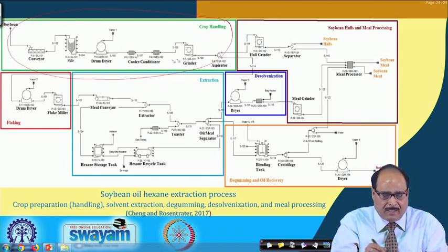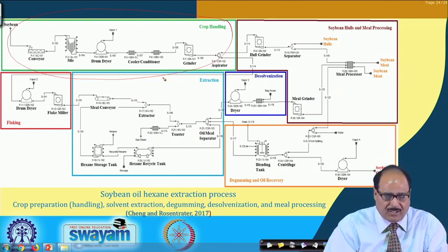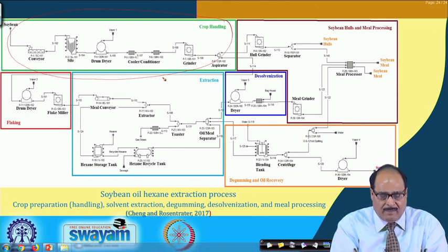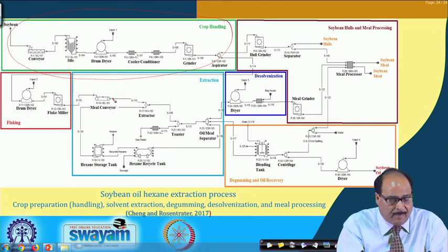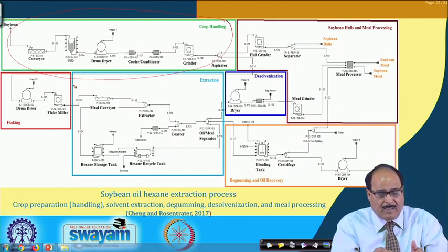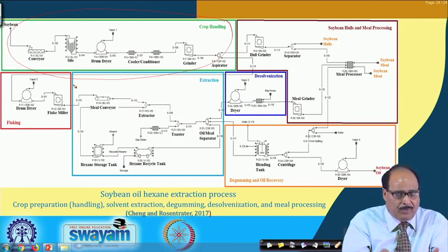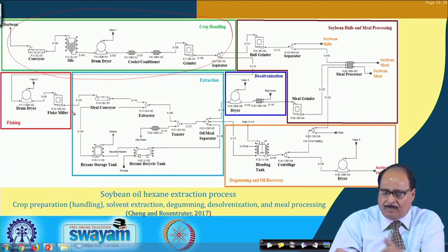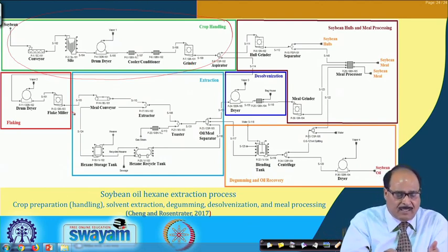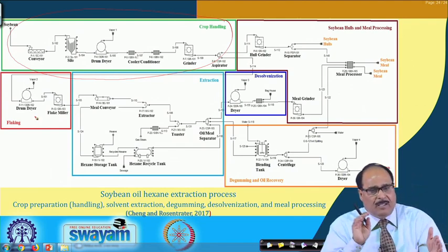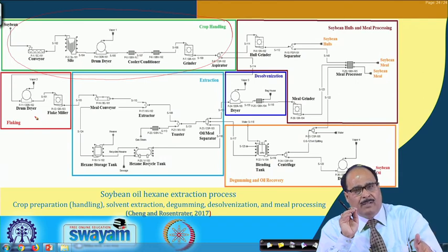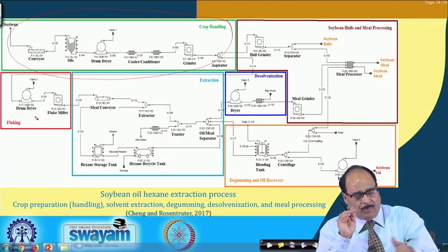After that, this section is the extraction section, where the prepared meals are fed to the extractors, all right. Before the extraction processing, if this is a press mill, it is fed to the press; or in solvent extraction, before passing to the solvent extraction, the material is passed through the flaking rolls or pelletizing units, and these porous flakes are passed to the solvent extraction.